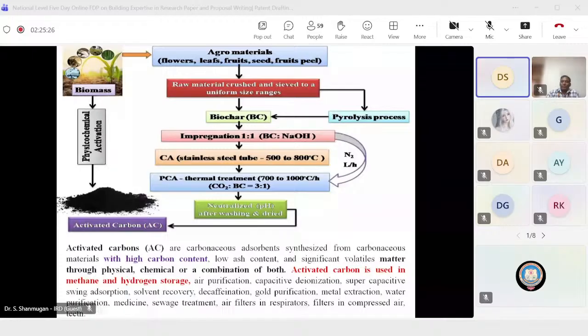Given some porosity, you can prepare some basic characterization. Then the characterization is FTIR, XRD, AFM, and SEM, with XRD as per the basic characterization rule. After that, you can see how much porosity you can get for energy storage. Based on the characterization of the activated carbon, you can do some physical and chemical interaction for some advantage of the material. You can process that material and see the characterizations. Okay, so this is the classification of the activated carbon.